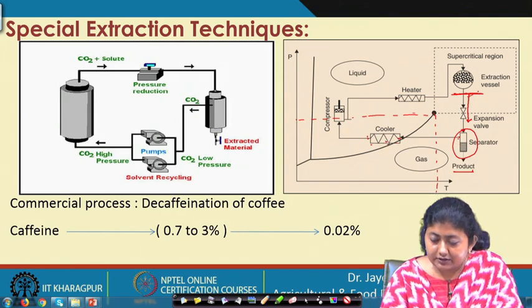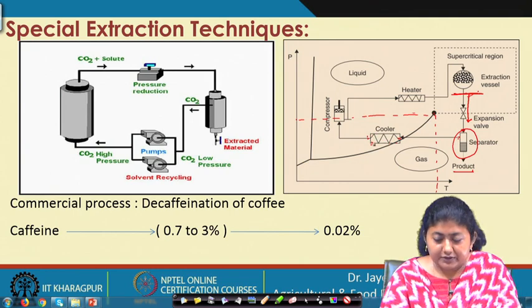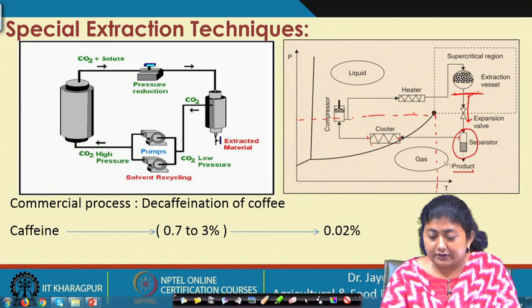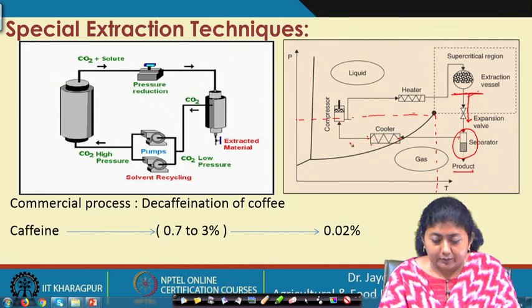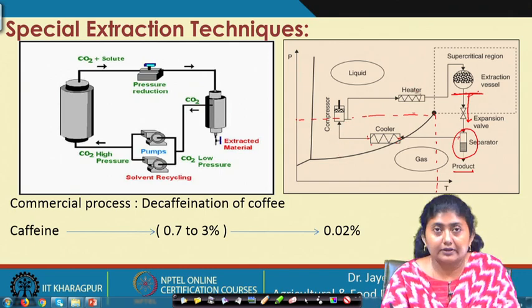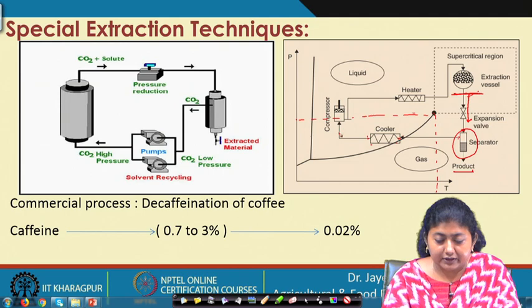There is a heat exchanger here that helps in the liquefaction of the carbon dioxide, and after that all the liquid carbon dioxide is taken to a tank. Since we need to increase it from the lower pressure to the higher pressure side, we increase the pressure by a compressor.